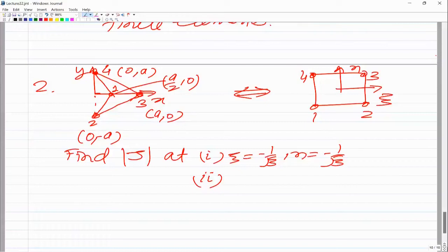The interior angles can vary from 45 degrees to basically say 225 degrees. That's about the angles, and the side ratios could be 1 to 8. So that's the maximum distortion which is allowed. If the element shapes are distorted more than that, then your finite element results are not going to be accurate. So the purpose of this is to just get an idea that the Jacobian can become negative, which is undesirable. That would give erroneous results.